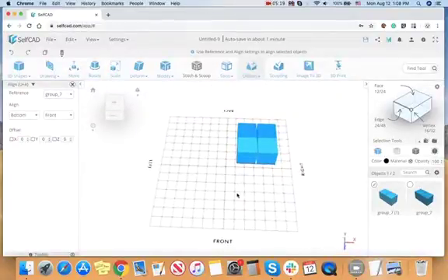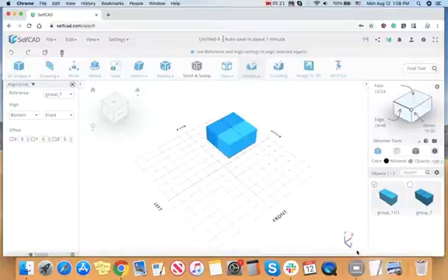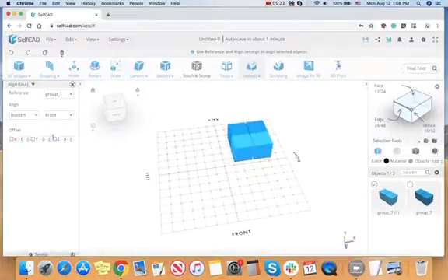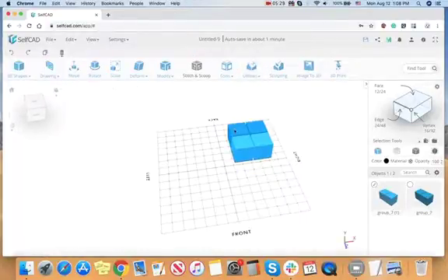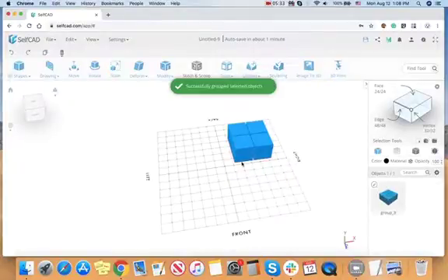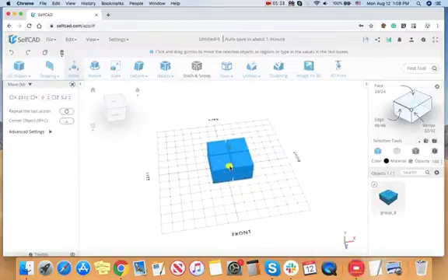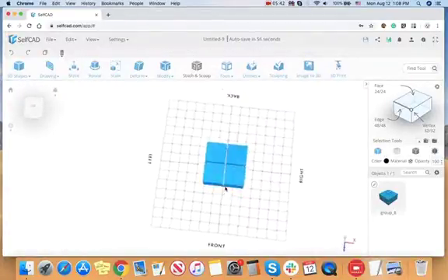But I have to look now at which axis it is. At the moment, I'm dealing with the Z-axis. So on the Z-axis, I enter 6.4, and in this case, it's perfectly aligned. So now I can select these objects as well, Command G, and I have it grouped, and now M to move it. I can start moving it, and I can center it. And now you see we have this perfectly aligned object.